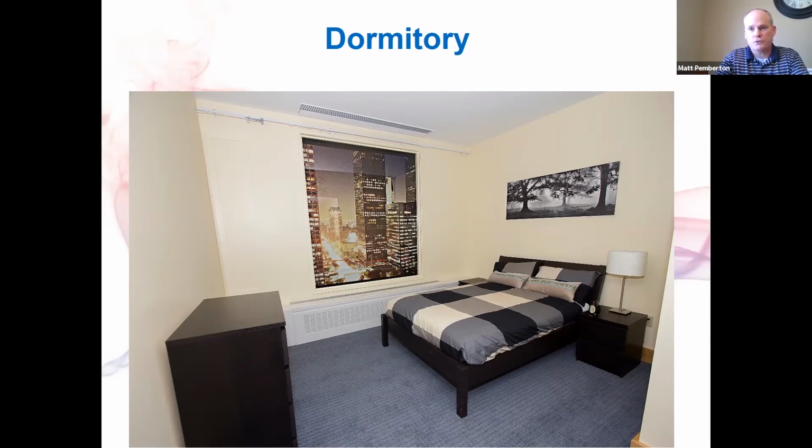Certainly true. Well, and to augment that answer, there are certain ways that you can set up the systems in order to help provide economization. I've often seen laboratories where you have an area, let's say right in front of the lab hoods themselves, where you've got some high loads. You could use chilled beams, and then with other diffusers throughout the space, laminar filtered diffusers, if you'd like, you can provide neutral air to the space to meet your air change requirements, but still have a ton of energy savings from what you're actually sending to the lab itself.